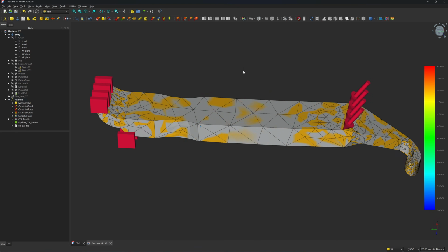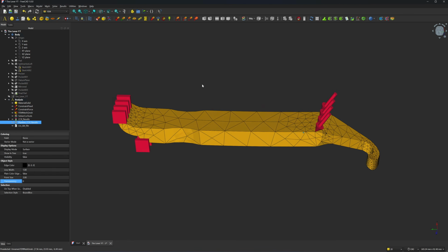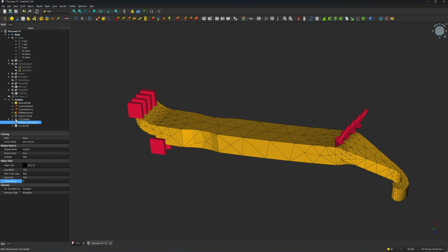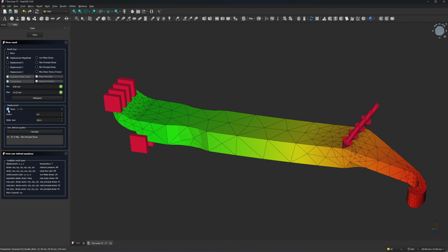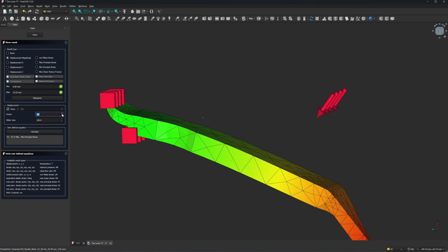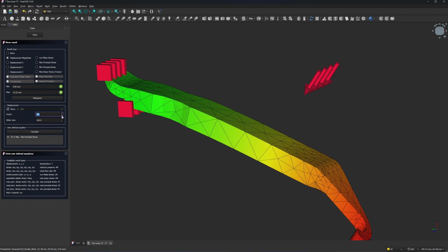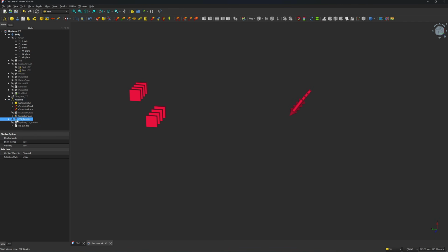So now you have the result. Let me turn off the pipeline CCX. Now you see your mesh, your fixing point, and the force. I will double click on CCX result. With this, click on this placement, click on show, this check mark here, and then you can simulate the movement of the lever. See here? So when you simulate the movement, you know which part requires a stiffener, which part requires a thicker dimension. Okay, close this one. That one we'll be using for simulation.